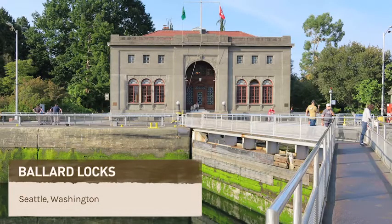Let's look at how to incorporate your vanishing point and your eye level line into a simple 3-step process to create the accurate bones of your architectural sketch. Now I'd like you to think like an architect, and instead of starting with a detail or a piece and growing your sketch, start with drawing the big shapes that form the buildings and spaces, the rectangles and squares. This is important because it creates a road map for your sketch, and it shows you within the first few minutes where you're going with your sketch, if the proportions are correct, and if it will all fit on your page. Let's look at this image of the Ballard Locks in Seattle, Washington.